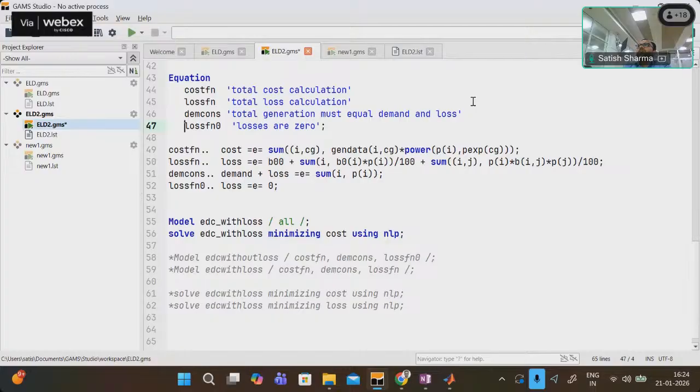Sometimes the dual will represent the market price. How will marginal value be interpreted? Yes, I will go into that part. Let me tell you, if our objective is cost minimization, social welfare maximization, or profit maximization, then the dual variable with respect to the power balance equation represents market price. So I will update the same code to solve the market clearing as well.